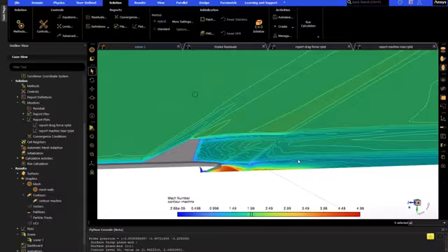To probe specific regions for quantitative results, double-click with the right mouse button, and the solution field value will be printed in the console, showing the max and min of the probe range. Here, we see the bulk free stream flow is Mach 2. The shock emanating from the fin is the result of an abrupt velocity change to Mach 1.9. The wake region outside the jet and behind the fin is subsonic, and the jet exhaust exceeds Mach 4.